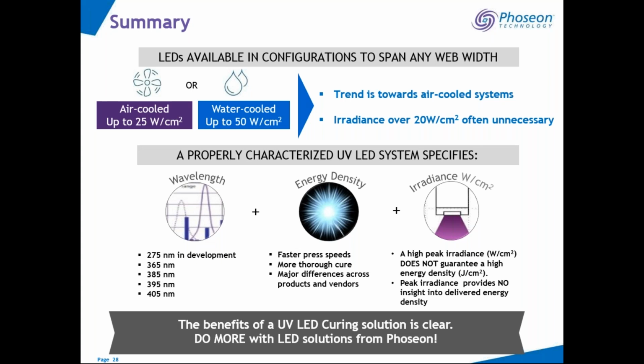Well, building on that, this question says for opaque whites or high volume UV, do they want more irradiance or do they want more dose? So currently, we've seen good cures. This is the metric where we can see 1,000 feet per minute with 20 watts per square centimeter. That's with the narrow window.